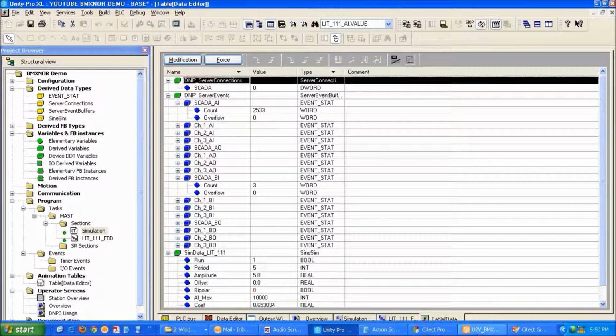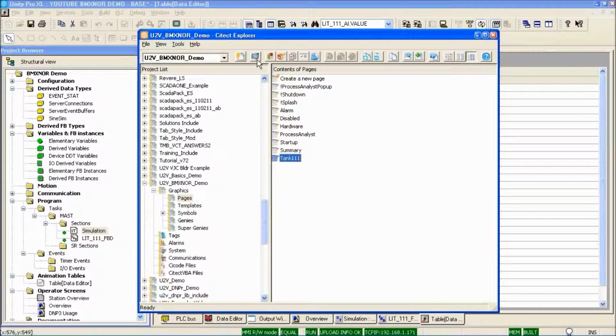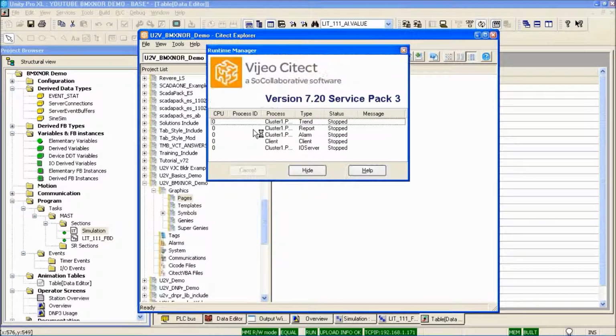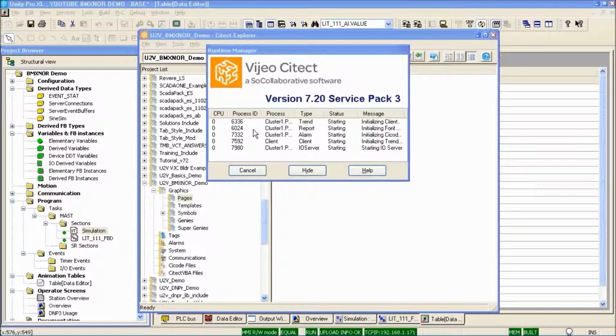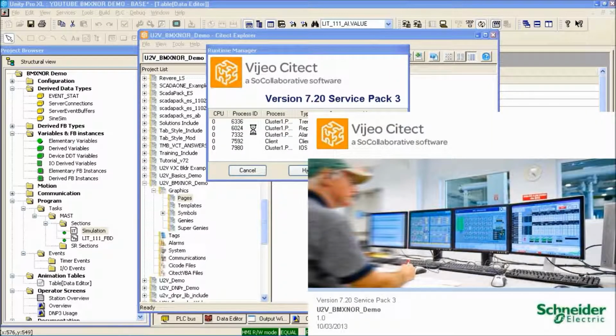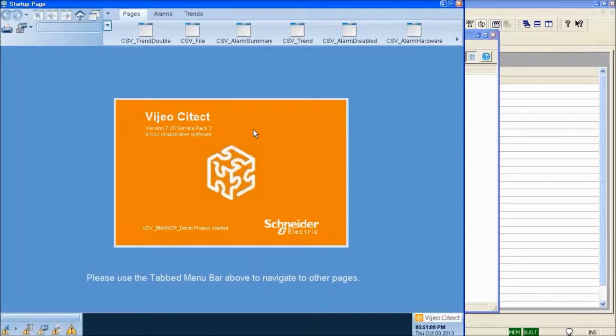What you will see is that even though the M340 will not get polled during the remaining time of this demonstration, the level transmitter data will be updated every time the level changes 4 feet, and alarms will be processed whenever they occur. Normally, the level in the tank will not change 4 feet every 24 seconds as it is here, because of the settings in the sine wave generator.